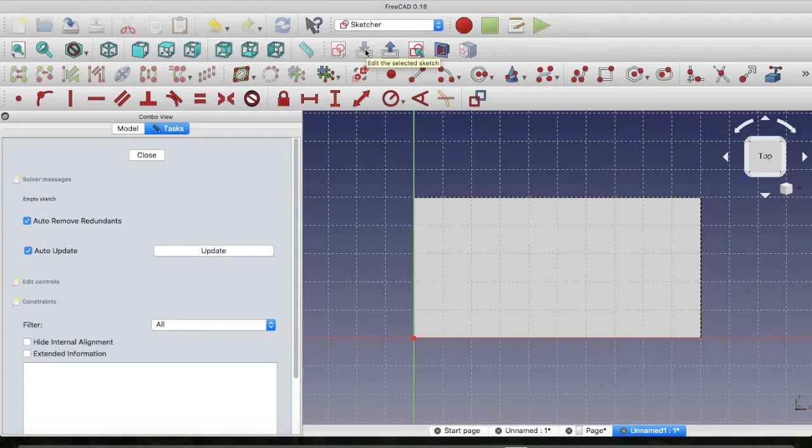Important point to note, we always need to select the particular plane on which we intend to draw the basic sketch and then have both the axes of reference by clicking the tool to create a new sketch. Next step is to click the tool for drawing a circle. As we click the tool, the circle command is enabled.